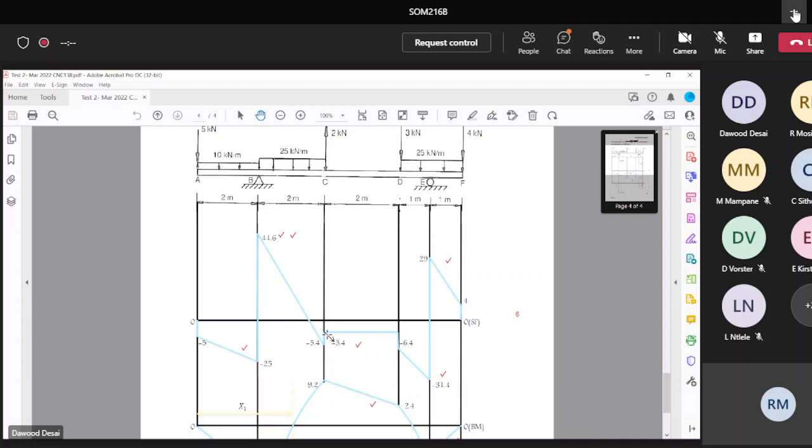Then after that, people, you calculate the bending moments at each section. It's a summation of bending moments to the left-hand side. So you can take this down, you can take a photo. BMA, of course, is 0. Bending moment at B is very easy, minus 30 kilonewton meter. Bending moment at C, 9.2.